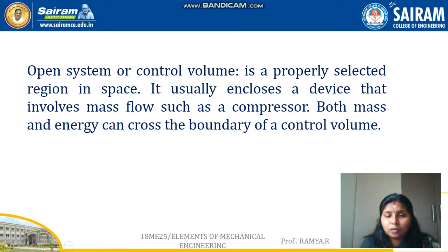The state of a system is the condition of a system at a specific time, which can be identified by values of a suitable set of parameters like pressure, volume, temperature, mass, etc. So at this moment, in this room, this is the temperature, this is the pressure, this is the mass, this is the volume. All these things put together are the state of a system. And the next one is the cycle. A thermodynamic cycle is defined as a linked sequence of processes. So the continuation of processes that take place within a system is called the cycle.